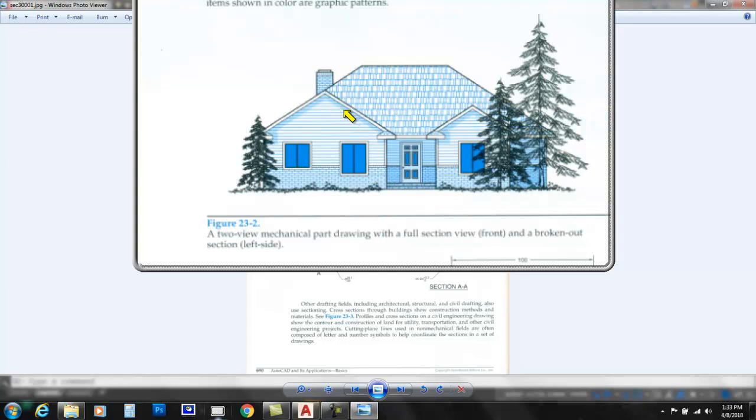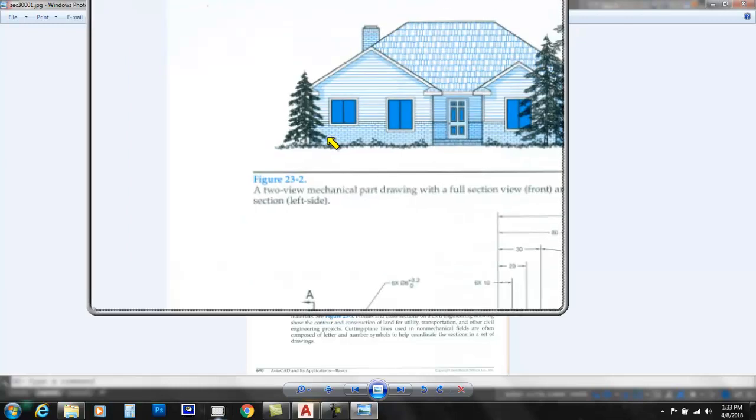In order for me to get this, I would have to temporarily draw a border, right? Because hatch has to be contained in an area. I would apply my hatch, and then my advice is to not erase that border, but put it in a layer and freeze it or shut it off. Because you might need it later, and if you erased it, it's just a bigger headache to get that back in the exact spot. Alright, but that is the effects of transparency as well.